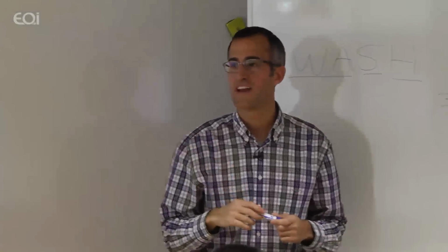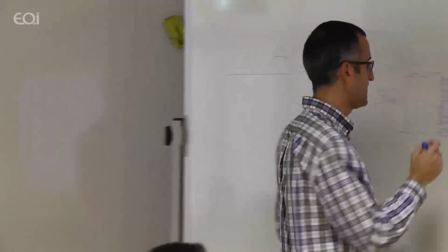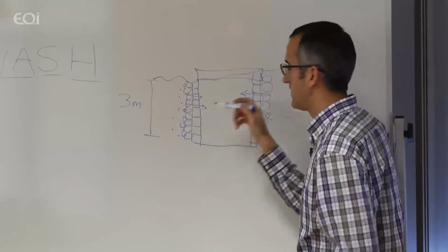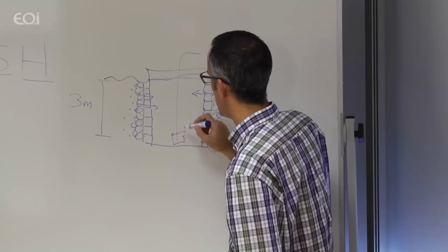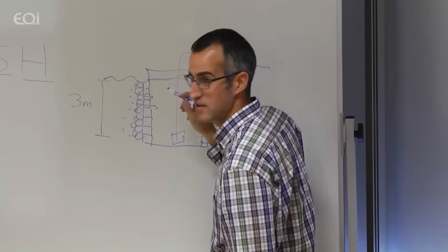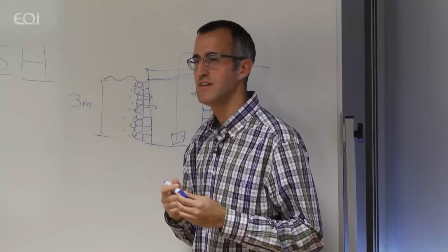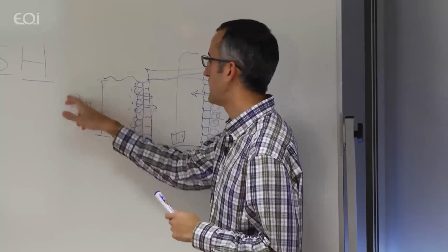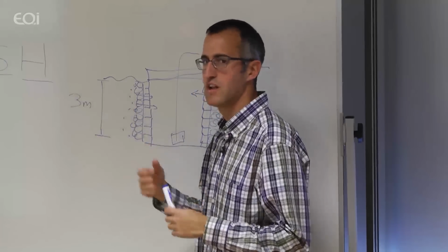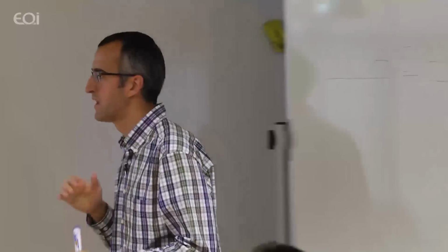And how do I get water from this excavated well? You have some options. Just with a rope, no? Or even with a manual pump, or with a Mecate pump, all these pumps that I will show you on Thursday. But if we are talking about 3 meters, you can use a lot of manual pumps that you will see. Okay.